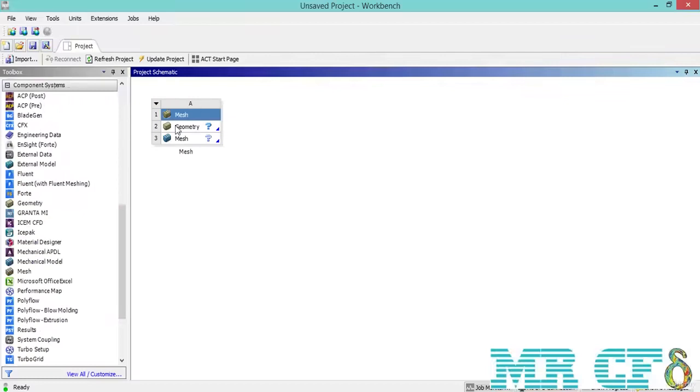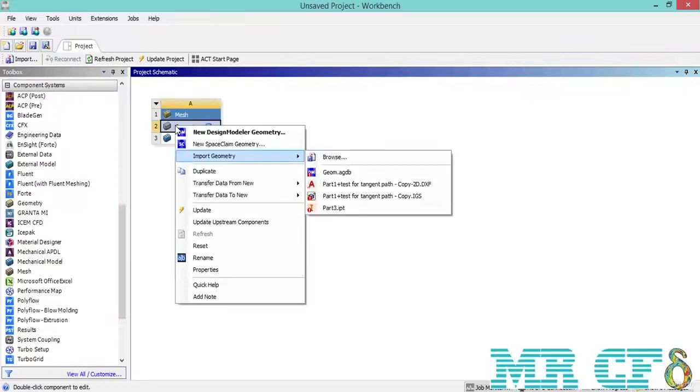After defining and selecting the desired unit, we right-click on geometry to select the desired drawing software. The built-in software for drawing geometries inside Ansys include Design Modeler and SpaceClaim. You also can import an external geometry using the Import Geometry option, in which you can import geometries from software like SolidWorks, CATIA, and Inventor.